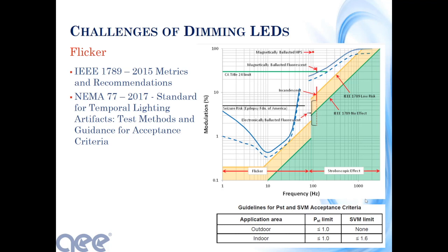You have to remember flicker is dependent on the waveform, how you decided to dim it. It's dependent on the duty cycle. It depends on how often the product is being turned on and off. So multiple things go into determining whether a flicker level is okay. You can say 30% flicker is okay, but only at certain frequencies. So that's why I consider it a convoluted curve.